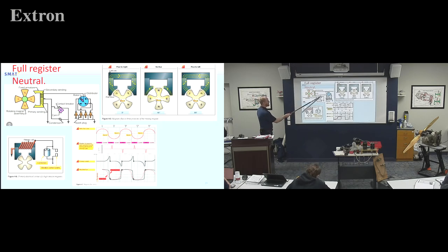And if we look, oh yeah, look at that. The contact breaker point is just opening right now. So we are about to make a spark, and if I look, I can find the spark there. So our points are opening, which means the field is collapsing from the primary, because the points connect the primary coil to ground.